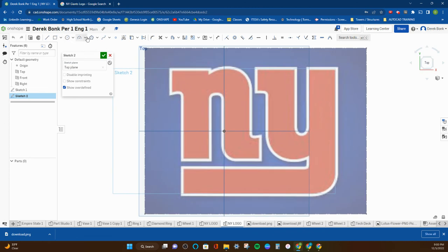also has the ability to be made with different types of arcs. If I go back into the sketch, I have sketch 2 lit up here. I'm on the right layer and space here, and I can pull things like this curve with something called a conic arc, and then I can use the same tool while I'm at it to bend any other arcs. This is not nearly as accurate as what I just demonstrated, but that's just the other kind of way that you can look at doing something like this.